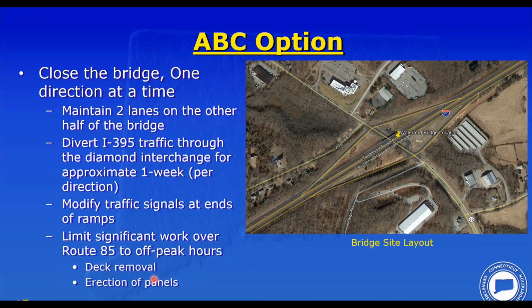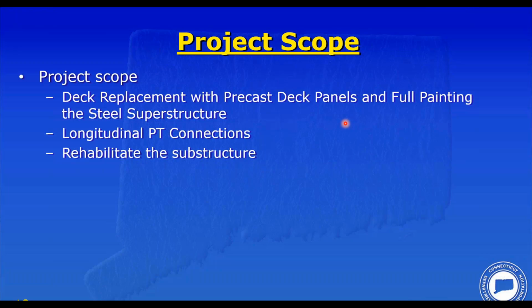And the thought was we can use off-peak travel hours to do things like deck removal and erection of panels. So the thought was maybe we can keep 85 open. So the project scope, as I said before, was honed in on as a deck replacement with precast deck panels and full painting.